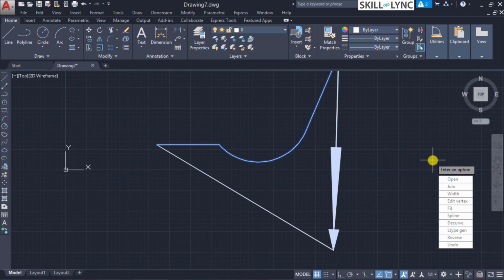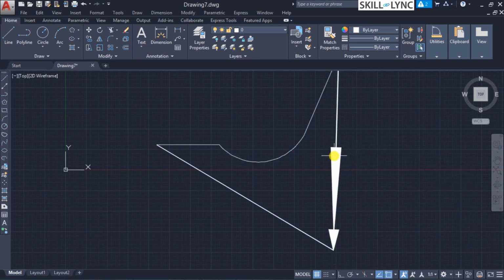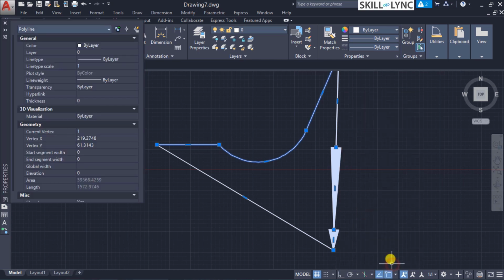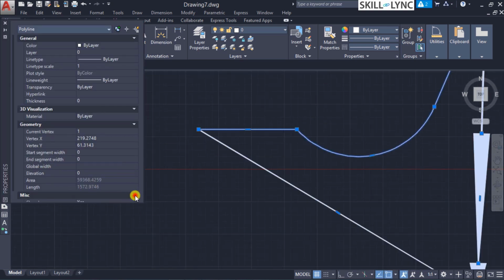So first we'll explore why this PEDIT command is used. As we said, it is predominantly used to modify the polylines that we have drawn. So we can edit using PEDIT, or also using the properties palette or grips, that is, editing with grips. If you double select the object, this is what you call grips, that is, based on selection of the grips you can modify the object that you want. Then also the properties that we are speaking about, right click and then changing the properties, wherein we can specify the vertices and so on.